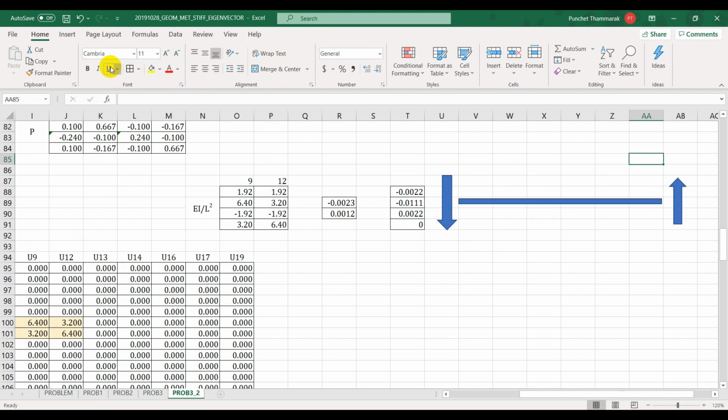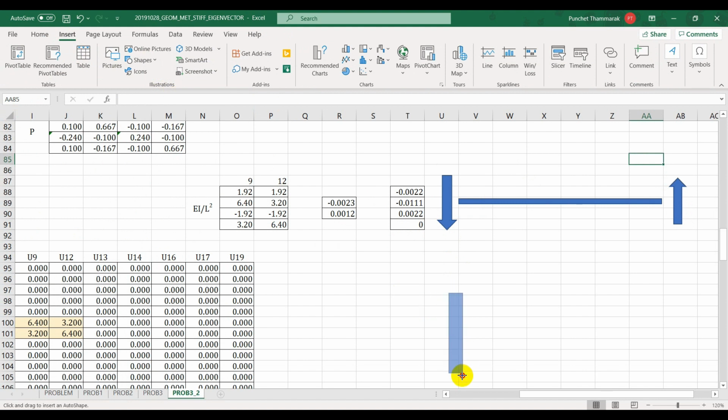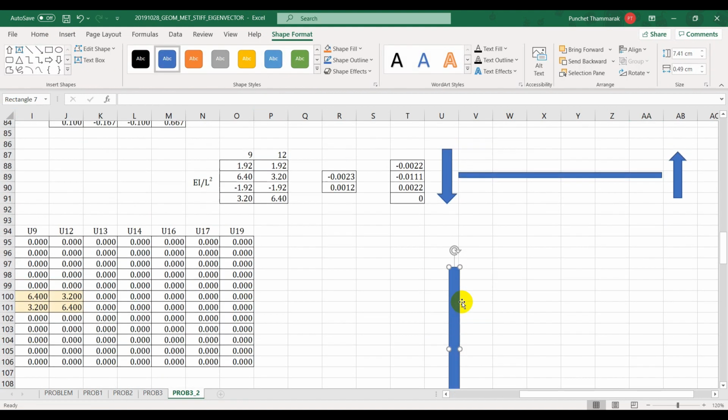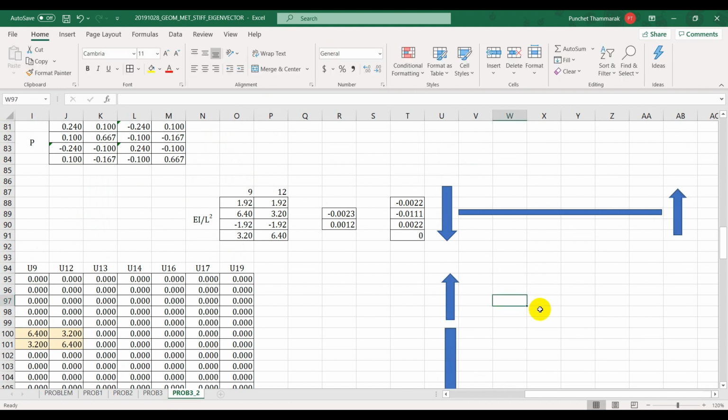That means when you consider the column which is below the beam, okay, column is here. On the column, the load will be acting like this. Okay, equilibrium. What acts on the beam like this will act on the column on the opposite side. The beam feels that it is anchored down, so the column feels that it is pulled up, right?